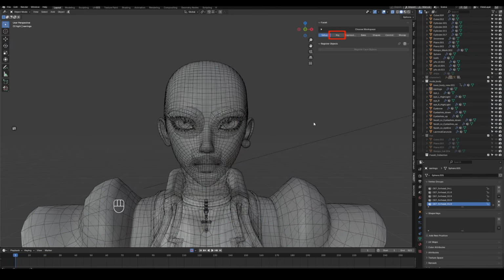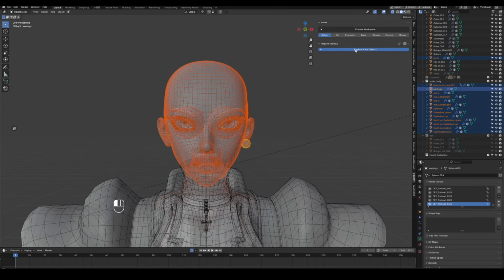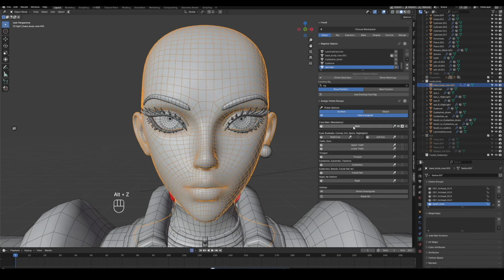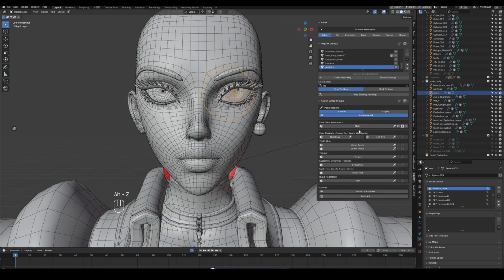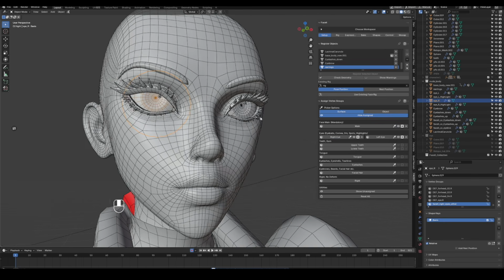Facet is mostly just following the menu in order. Click Register Face Objects. Select the head mesh, click the main button, and assign it as the head. Then assign the left and right eyeballs. And I also include the eye highlight parts. Next add the upper teeth, lower teeth, and the tongue.